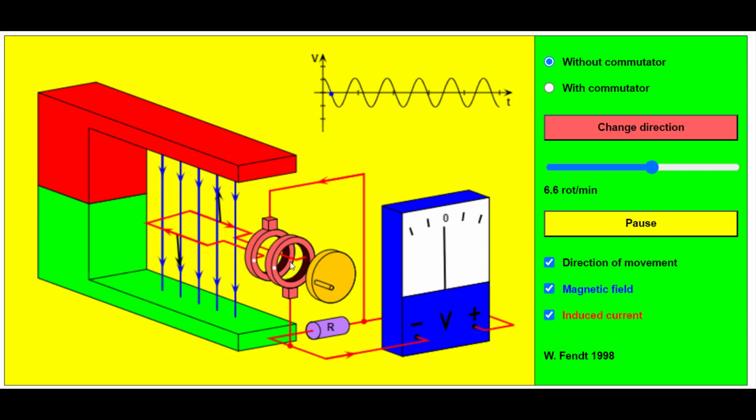Now what we are doing is that we are producing alternating current electricity. As you can see, the potential difference is negative, then it's positive, then negative, then it's positive. And we can also see that on the reading of the voltmeter here. The idea here is that every brush is connected to a slip ring and it is always connected to this loop of wire. So when the loop is rotating, it is producing electricity, but this electricity is once going in a certain way and now it's going in a different way. So when it goes back and forth, as you can see, when you look at the arrows right here, we are producing alternating current electricity.